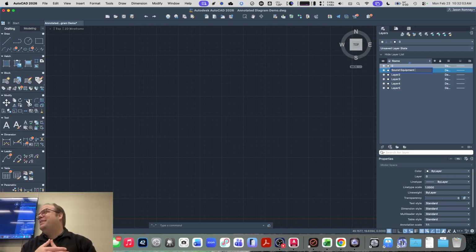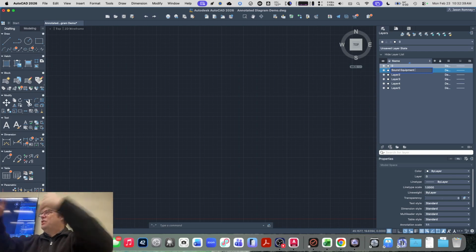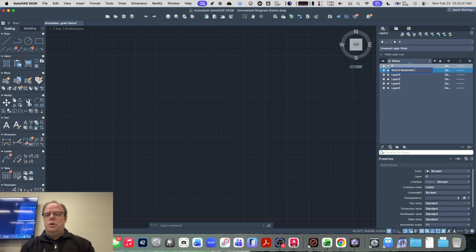I don't want, if I have another person that is a sound person that maybe took the exact same class that I did, and I'm working with them on a project and we're sharing files back and forth, and they have their layers named the exact same thing as my layers because they took the same class and did the same thing I did, I don't want to have to worry about that style conflict. So it's a good idea to add some unique thing to the end of your layer name, because AutoCAD, if it sees the same name, is just going to merge it when you import that drawing. So you can do whatever you want.